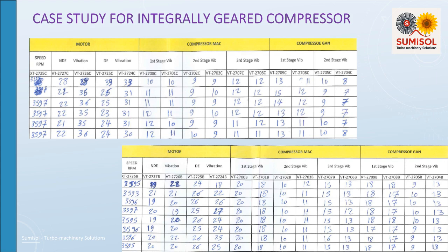4. During balancing, plots and spectrum should be taken out from System 1 and kept as snapshot if possible, which should be circulated and kept as record. 5. At least 3 readings should be taken for complete train vibration for repeatability check after balancing. 6. The person should be certified to carry out the work. After successful activity of field balancing using trim holes provided, vibration came under acceptance criteria.